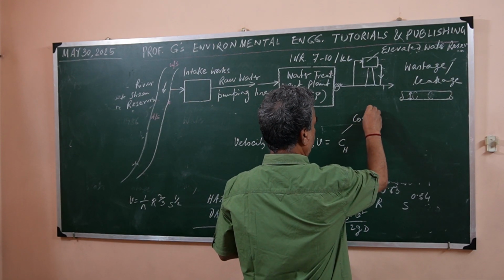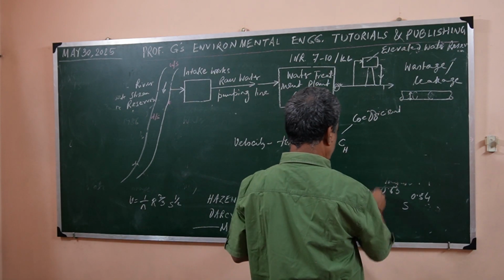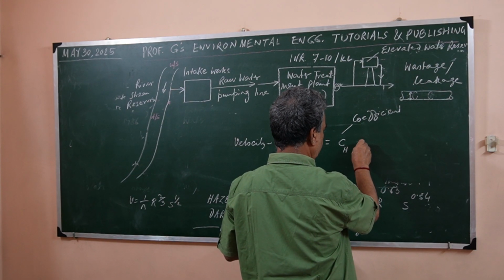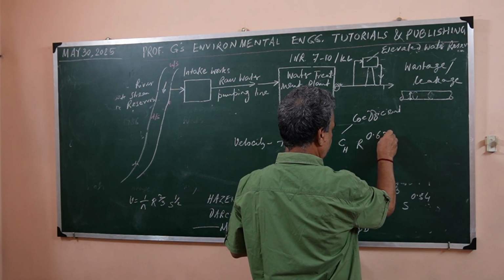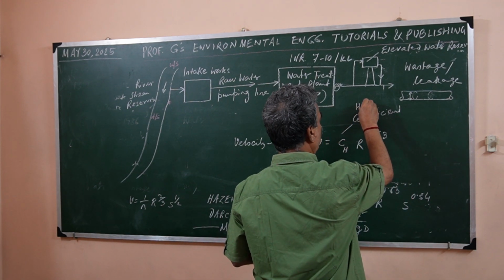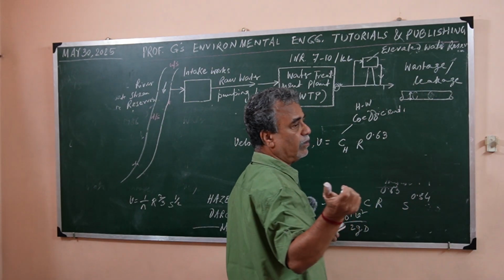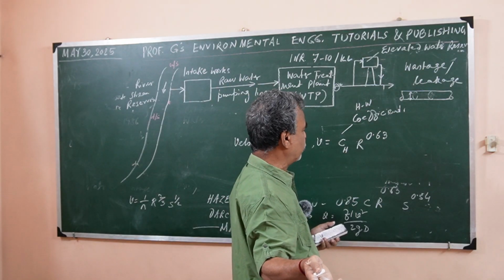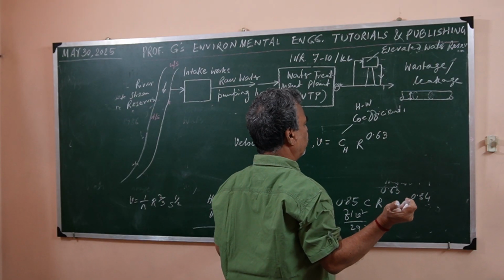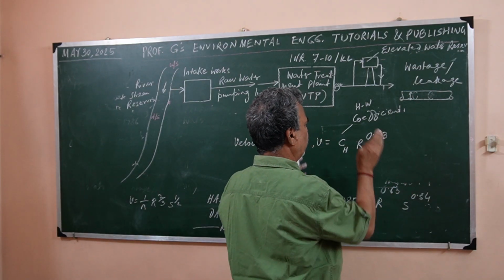And then this is R, means the hydraulic radius. So R that you see, that is to the power 0.63. This is the Hazen-Williams coefficient, and these coefficients you will get from the manual or any standard books, or IS codes also. That may be sourced from this standard literature also. More or less the textbooks are giving these values.